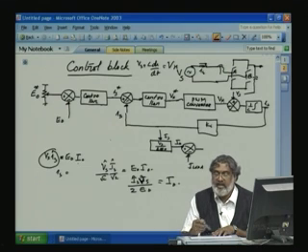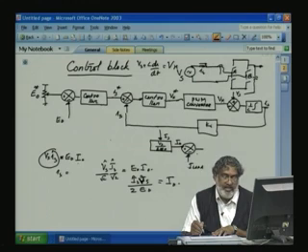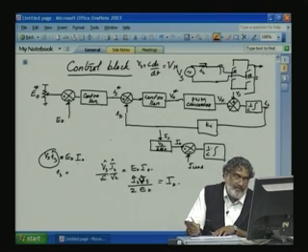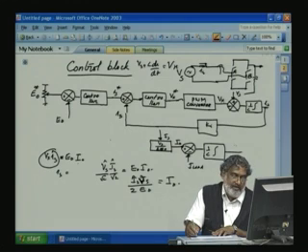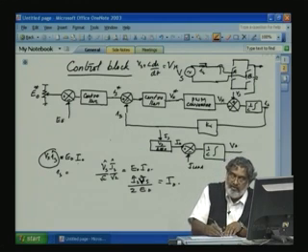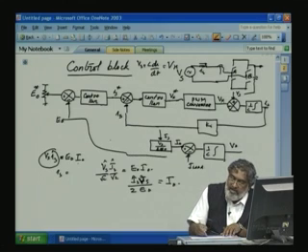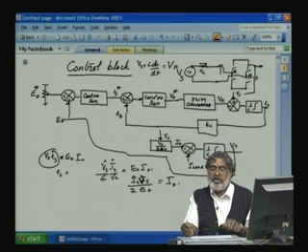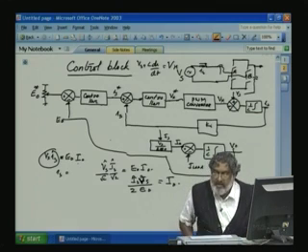So, unless that is indicated to the converter I0, there can immediately be a fluctuation in the capacitor voltage. So, this difference immediately goes to the capacitor. That will generate a ripple, 1 by C, this is the integral. That will give the V0 side. This V0 will feed back to this one. This is the complete block diagram for controlling the converter.